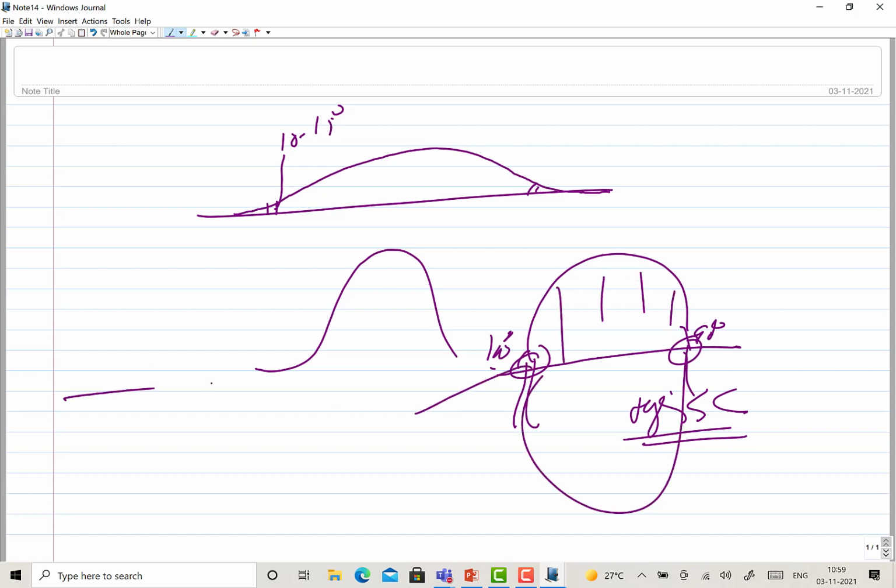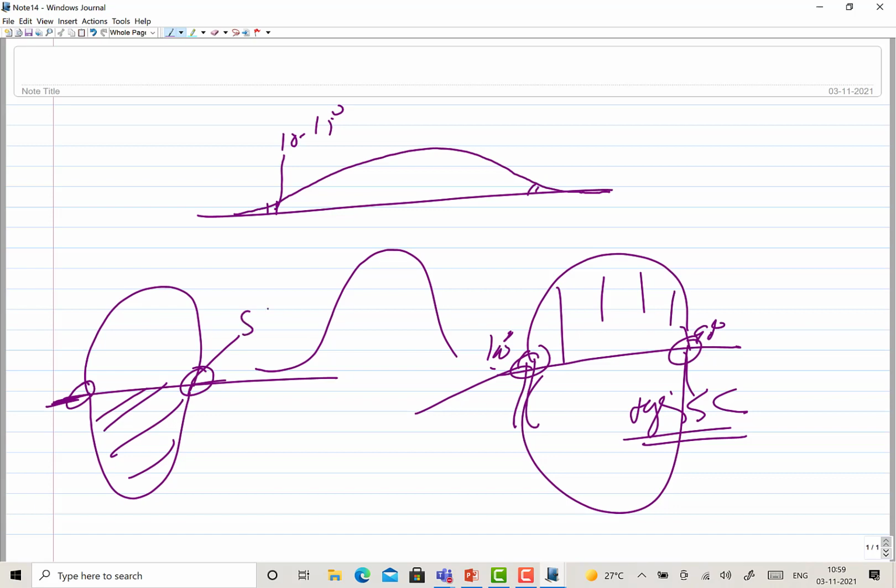So what you are having basically, the weld and the bead is like this. The weld is fine, but this section of the base metal and the weld bead will be highly sensitive to stress concentration. So the crack will be initiating from this location only. So high stress concentration at the toe of the weld will be triggering the fracture, will be initiating the crack, and this is particularly due to the improper bead angle.